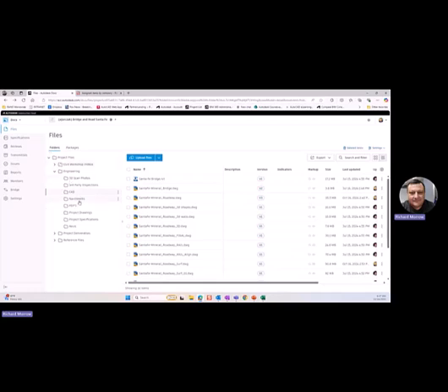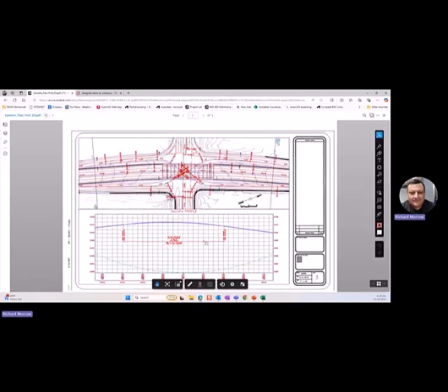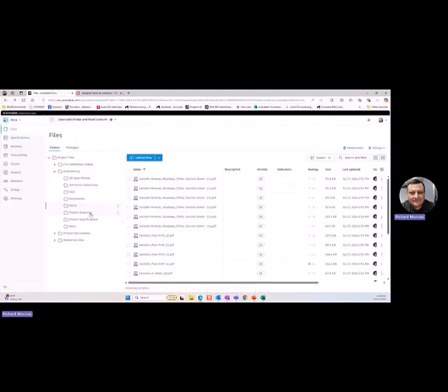Markups are easily done as well. So I can do a markup on the drawing there. I can come in here to my PDFs and look at a PDF and do a markup on a PDF if I wanted to. So if I wanted to make some adjustment on something in here, maybe I say we gotta clean up this text here, right? So I can put a text bubble there and do some adjustments there, or whatever it may be, but you have the ability to do those, assign those as issues and go through and do those type of things. So you have all that ability right there to assign those issues to a person or a group and things like that. You can also come in here with compared versions.